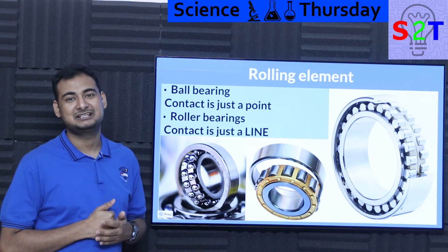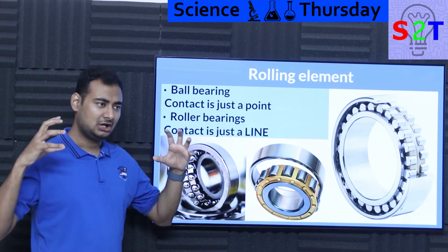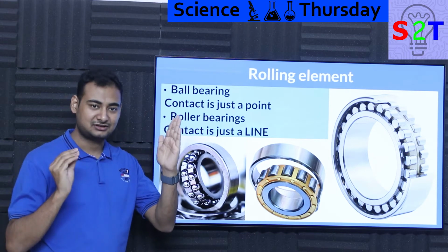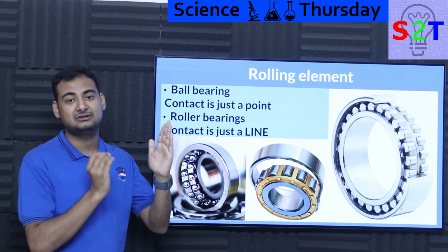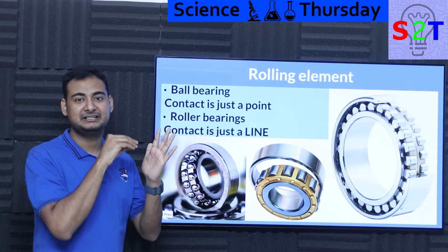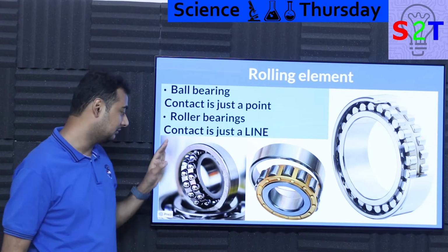You cannot make metal strong enough, or any ball rigid enough, where it's going to be like, I'm going to put 10,000 ton through this and it's not going to deform. If you put 10,000 ton on even the hardest steel or material that we know, it will simply dent it. You will end up getting stuck. So for more than enough scenarios, ball bearings are good enough.